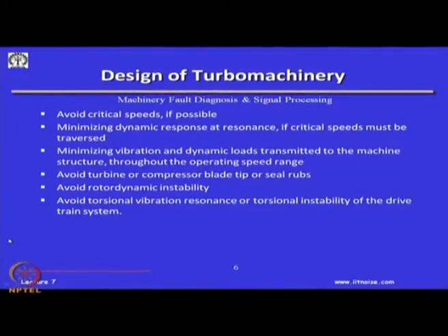So, as you can imagine, turbo machinery is a very complex mechanism, other than the fluid mechanics operations, the fluid machines part of it, wherein we have a certain energy coming in, certain energy going out, and then we get a thrust. But beyond that, there is a lot of engineering in designing a perfect turbo machinery as far as its dynamics is concerned: not rotating at its critical speed, how to avoid critical speeds, how to traverse up to high speeds, how to avoid instability, how to avoid rotor rubs between the stator and the rotors, and how to avoid multiple resonances in torsional systems. So, these are the complex issues of turbo machinery.